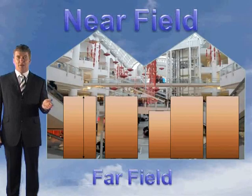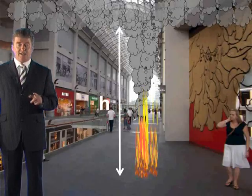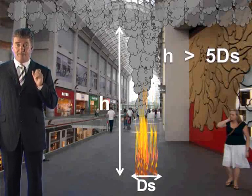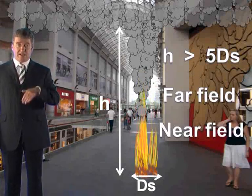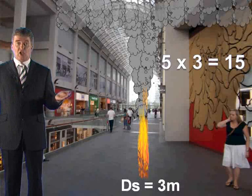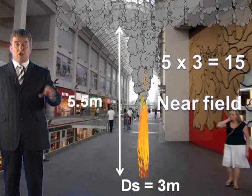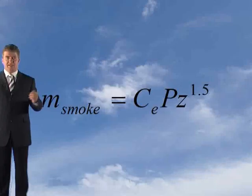Now next we have to decide whether it's a near field or a far field model. Don't forget, if the clear layer height is greater than the longest dimension of the source multiplied by 5, then it will be deemed to be a far field model, not a near one. If it's not, it's a near one. Those are the parameters. Now in this case, 5 times the longest dimension of the source, and it's assumed to be a 3 metre by 3 metre fire, is 5 times 3, which is 15. And the clear layer height is only 5.5. Clearly, it's a near field model. So we know that we're looking at the near field axisymmetric model. So this is the model we have to apply here.